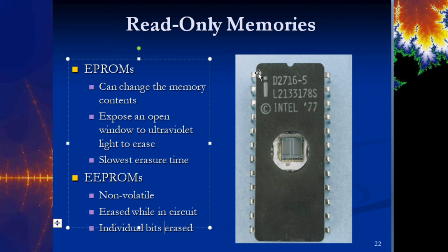This is what is used inside of PLCs, programmable logic controllers, to store not the program that keeps getting downloaded from the user, because that can happen thousands and thousands of times. This is the firmware that's inside the controller. If you have a certain controller, you want it to use a certain version of the software, and you may change it once a year, and that's it.